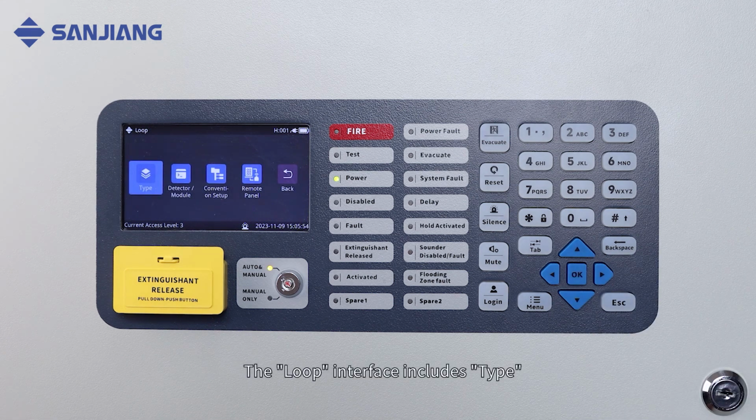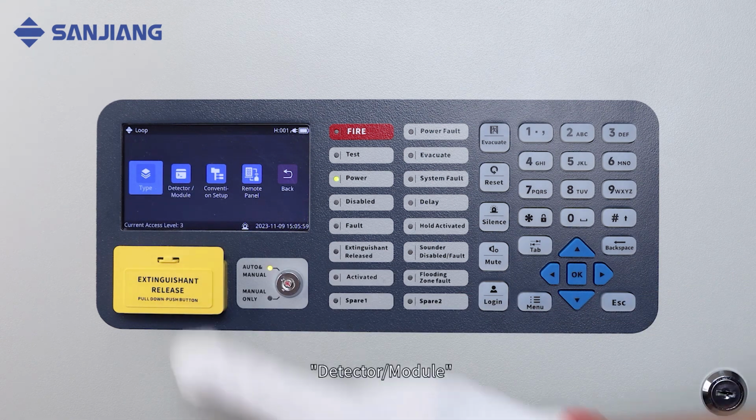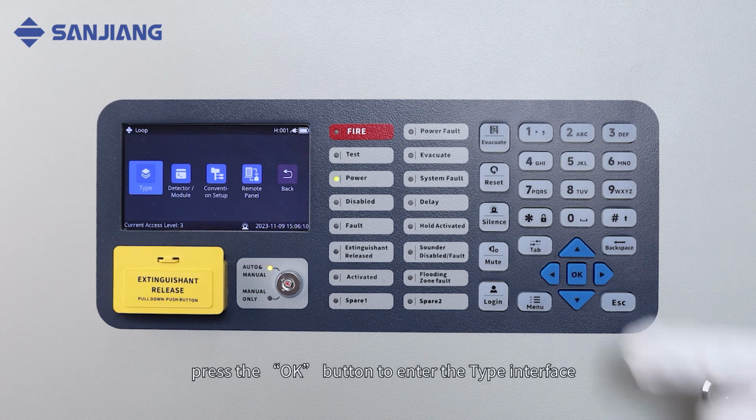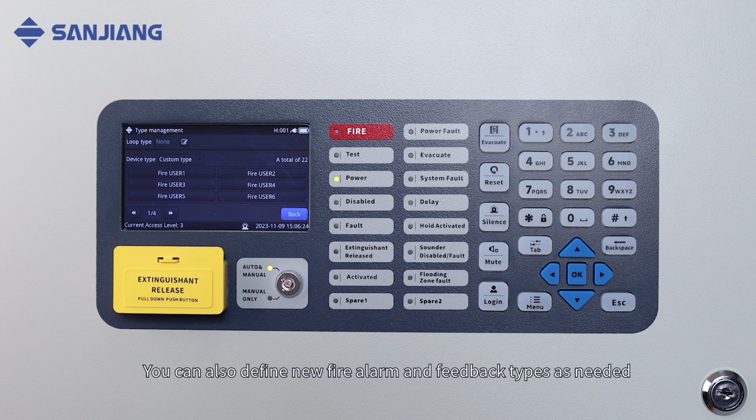The loop interface includes type, detector module, convention setup, and remote panel options. Select Type. Press the OK button to enter the type interface. You can modify the loop type, either Class A ring loop or Class B tree loop. You can also define new fire alarm and feedback types as needed.